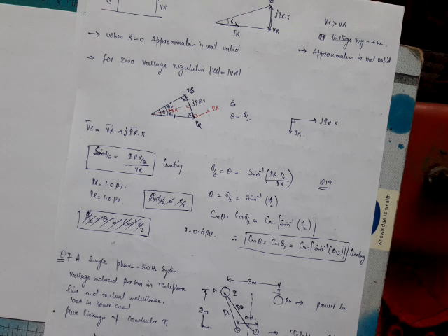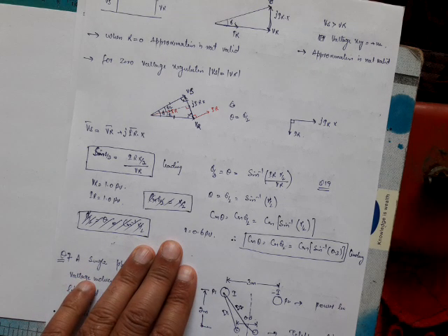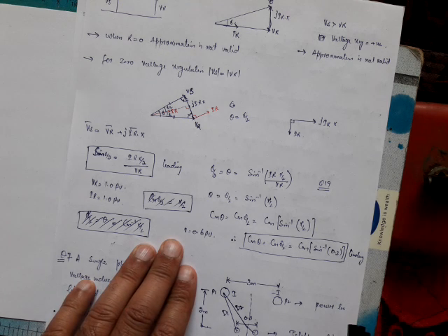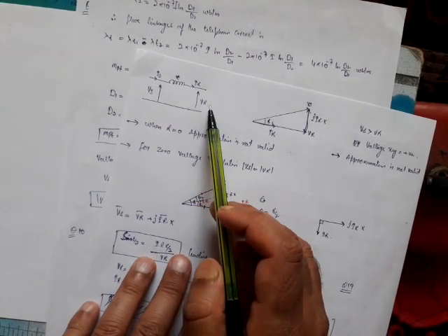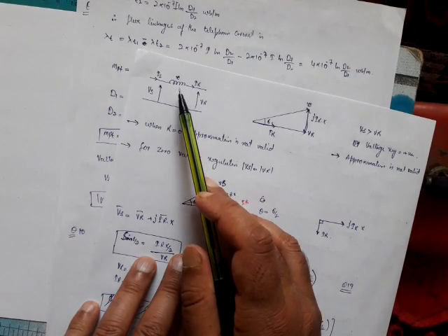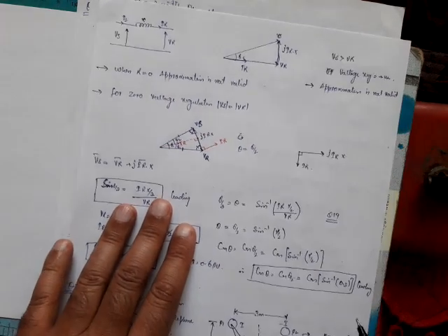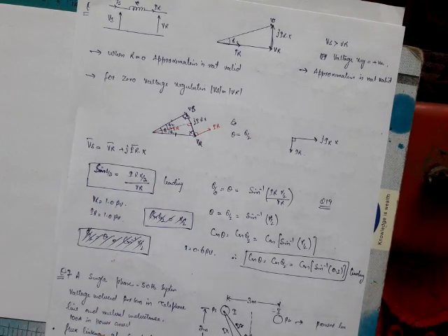performance of transmission line. In that it was asked what will be the value of the power factor if the voltage regulation is 0 for a system having R equal to 0, a pure lossless system. That is, VR is equal to Vs for this type of system. And what will be the condition of the power factor? So the power factor will be this, and in that case the voltage and this reactance were given in per unit.